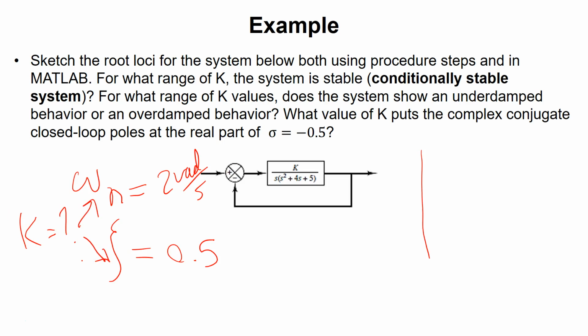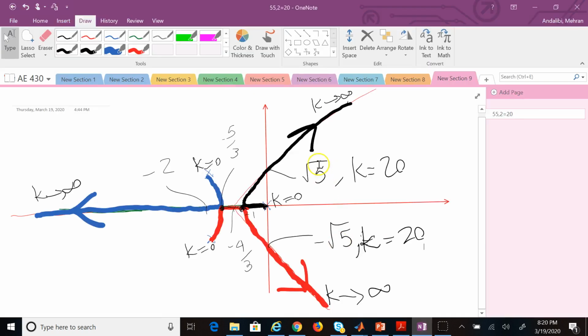And that's where not only do you have to have the root locus of the system, you also need to draw what? The loci for constant omega or constant zeta. And then let's say here, for example, if I want a constant zeta of 0.5, we learned that it's a line with an angle of 60 degrees.